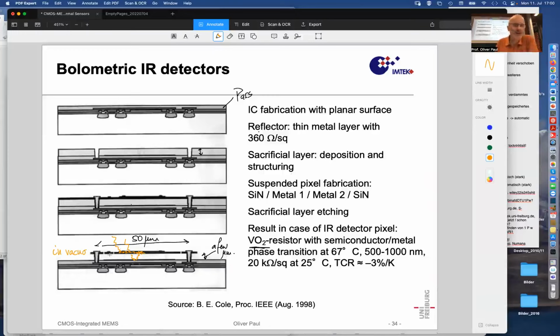The thermal conduction loss P cond through air should be excluded because the distance is so small that if this is filled with air, then you have delta T divided by a small distance times a kappa of air, a few micrometers, in the continuum regime of the conduction. This is at Knudsen numbers much smaller than 1. Then you have kappa of air 0.026 watt per meter Kelvin times delta T divided by a few micrometers. Oh, that removes that heat really efficiently.